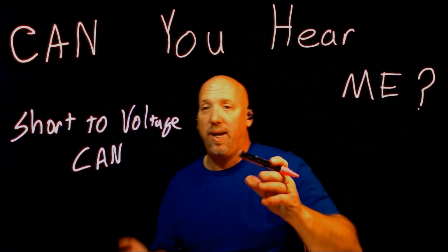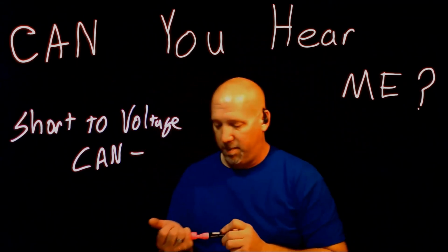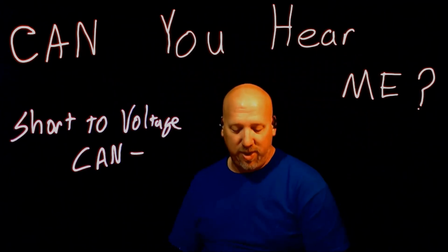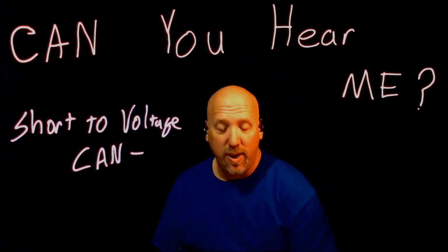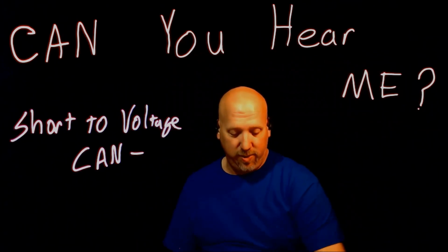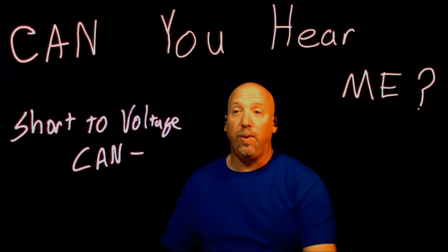A short voltage on CAN negative. This short prevents other modules from achieving the proper bus voltage differential needed for other modules to sense a message. Therefore, the fault results in no communication with any modules in the network, even though only one circuit is shorted.